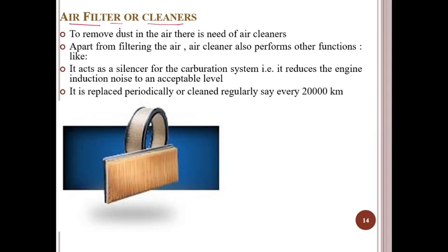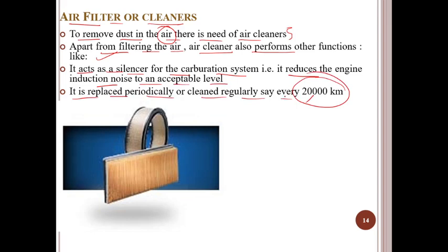Air filter or cleaners. To remove the dust in the air, there is a need for air cleaners. We require air cleaners whenever we pass air into the IC engine, diesel engine, or petrol engine. The dust comes with the air, so this dust will be removed. Apart from filtering, the air cleaner also performs other functions. It acts as a silencer for the carburation system. It reduces the engine induction noise to acceptable levels. It is replaced periodically or cleaned regularly, say every 20,000 kilometers.